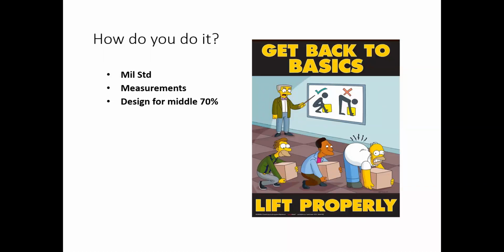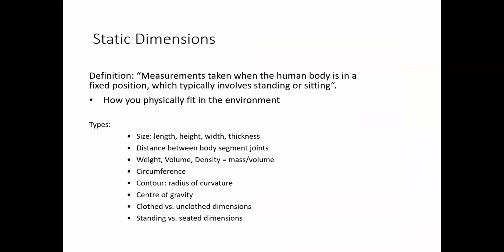system problems. How far can we see? What's our viewing cone? All those things fall under ergonomics. So, and there is a fair amount of work to be done on that in nuclear. As you saw in that original picture, nuclear control rooms historically have been these humongous rooms with all these different indicators. Well, you need to be able to see those. You need to be able to navigate to them, walk up to them, hit anything on the boards that you may need. So it's important to be aware of those.